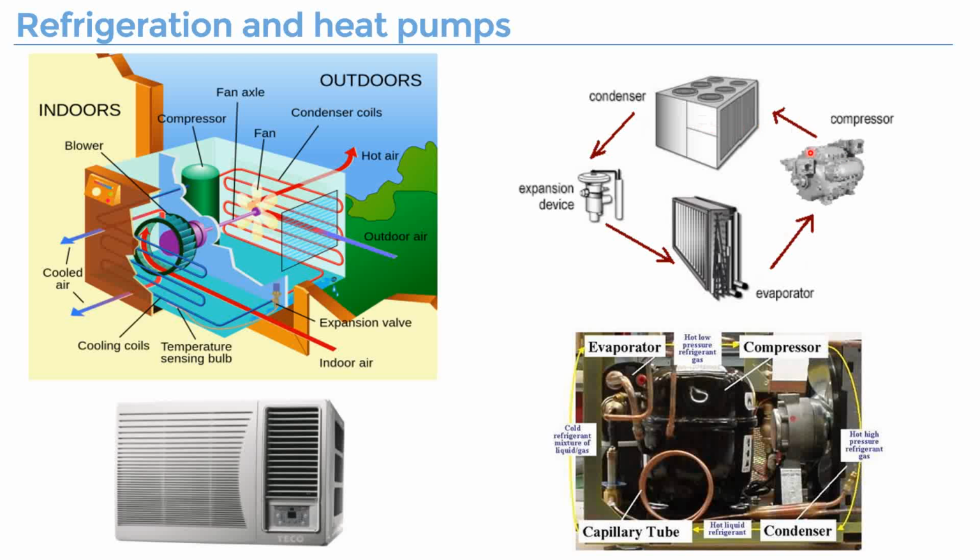That goes to the condenser. So basically the condenser and evaporator, these two things are just heat exchangers. The evaporator exchanges heat with some refrigerated space, so you have the cool, low temperature refrigerant going through. But in the condenser, because it's a very high temperature, it naturally transfers heat to the outdoor environment. So that's how it rejects the heat to the environment you want the heat rejected to. So that's a basic schematic of this system.